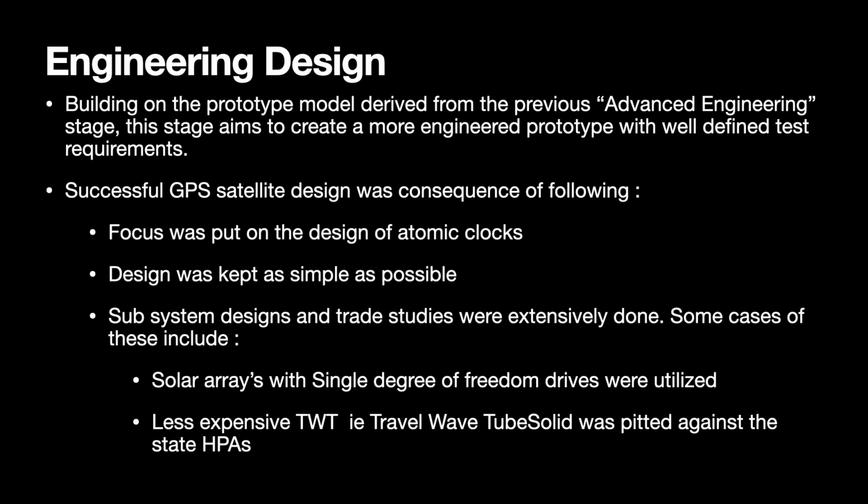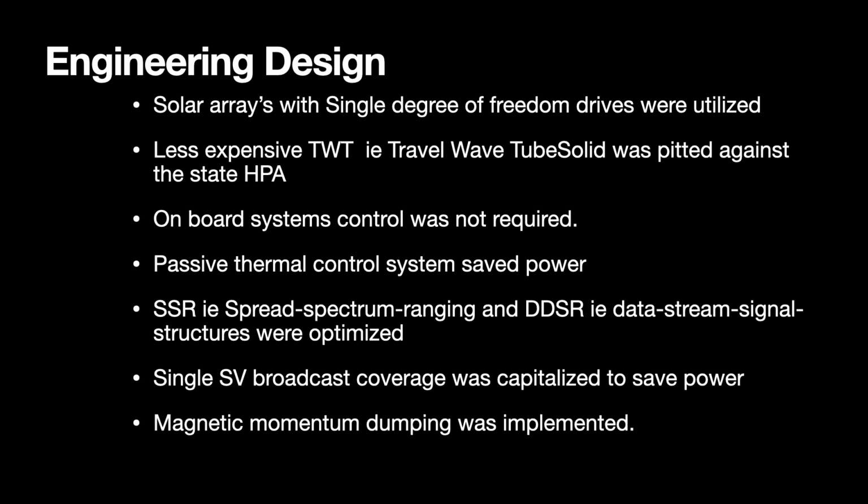The less expensive TWT, that is the traveling wave tube, was pitted against the solid state HPAs for improved life, removal of high voltage power supplies, and effective power consumption. Onboard systems controlling the navigation functions were no longer required.